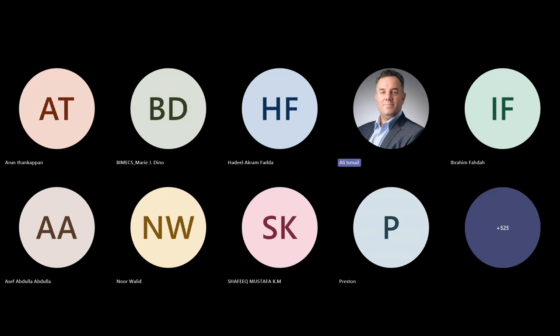If you are submitting a BIM model only for architecture and you are not mandated to submit a structural model, please add the stairs and ramps to the architectural model. If you are mandated to submit both disciplines, please feel free to move them to the structural model, because there are some regulations related to the number of steps and the threshold, etc., for the architectural design of stairs. That's why we need them in any case to be in the model.